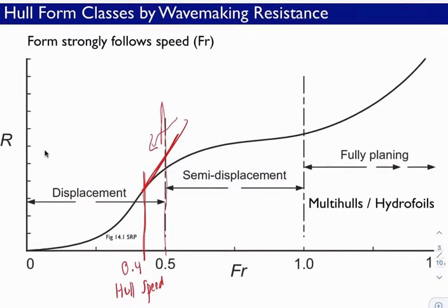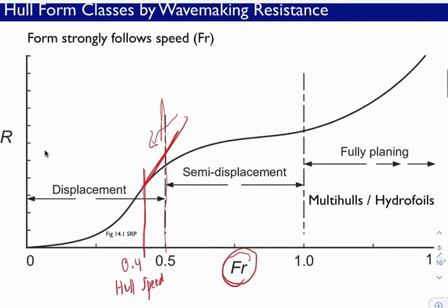The reality is if you want to keep progressing in terms of, and this is written in terms of Froude number, then you have to have hull modifications that actually reduce the displacement of the hull. So semi-displacement or semi-planing forms use lift, hydrodynamic lift, to actually carry some of the displacement of the hull itself to reduce the overall drag and allow you to get through this hull speed kind of barrier.